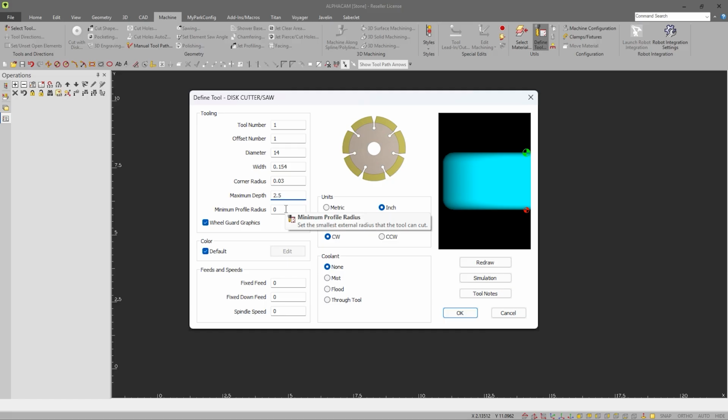than 2-inch material. This next field is only used if I'm cutting an arc instead of a line. I'll restrict myself from cutting anything smaller than a 24-inch radius. And I won't be using any graphics of the shroud in this part 1 video. In some of my common settings, I'll use inch, spindle rotation clockwise, and always have flood coolant on.